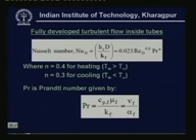So, Nu is the Nusselt number, and it is equal to Hc d by Kf, where Hc is the convective heat transfer coefficient, d is a length parameter, and Kf is the thermal conductivity of the fluid. And on the right hand side, you have the Reynolds number Re, and also another dimensionless number known as the Prandtl number. Prandtl number Pr is Cp mu f by Kf. All the properties are those of the fluid, that is why the subscript f stands for fluid.